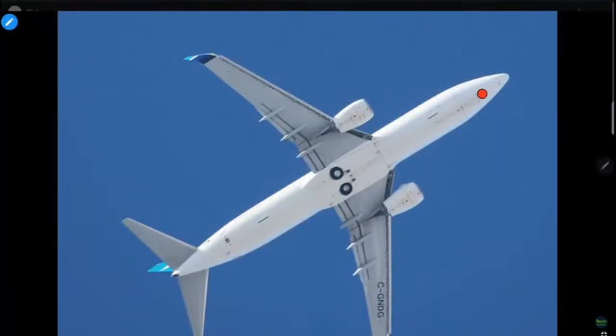But in all the videos that I showed of the EMAS system, you notice that the landing gear was down. The landing gear is a point of focus of force, high pressure, breaks into the tiles and comes to a stop. In this flight, the landing gear was not extended. This is the underside of a 737 to the main landing gear here. The nose landing gear is behind a door up there. Now, in the videos that we've seen, there's no evidence of any open doors or anything, so it appears the gear was never extended.